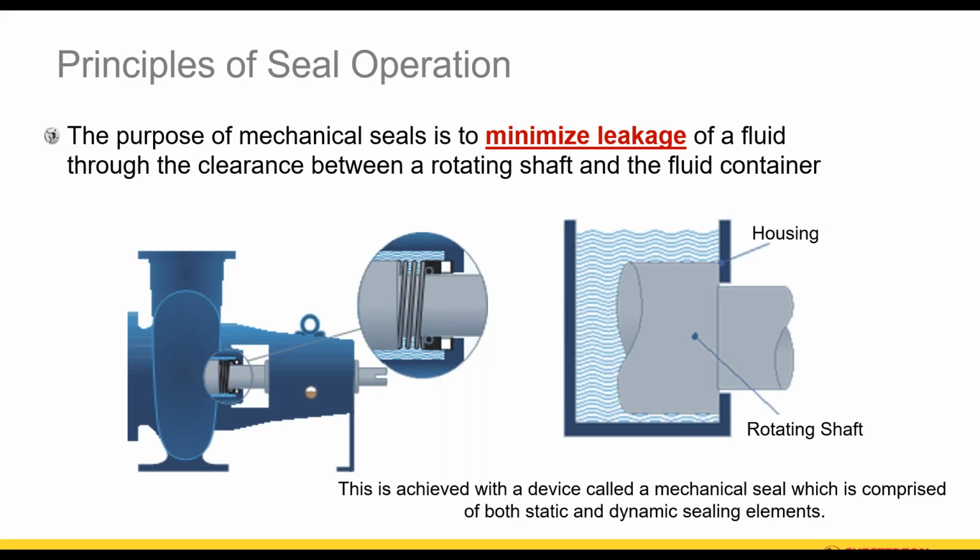But taking a step back, all sealing devices actually leak. We have data that proves that. Whether it's a gasket, an O-ring, a mechanical seal, a lip seal, they all leak a minute amount of fluid when operating properly. They have to or they will not work. So just be careful whenever you tell your customers or say something about being leak-free.